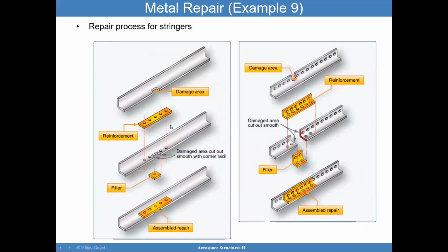Yet another example for stringers. So you have, again, a reinforcement from behind, and then at the top you bring it in like that. So again, in this case, you have a shape that matches that. And this is your fitting, and so you're going to cut it apart, bring this in, and then bolt it through this reinforcement.